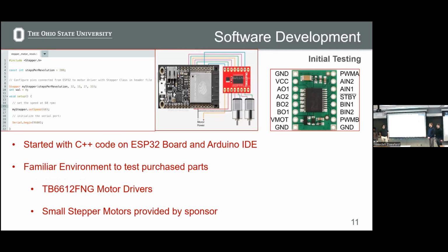So the start to accomplishing the stepper motor approach was first testing all of the components purchased by our sponsors. Basically, the H-bridge stepper motor drivers, again, purchased by our sponsors, and the small stepper motors themselves.